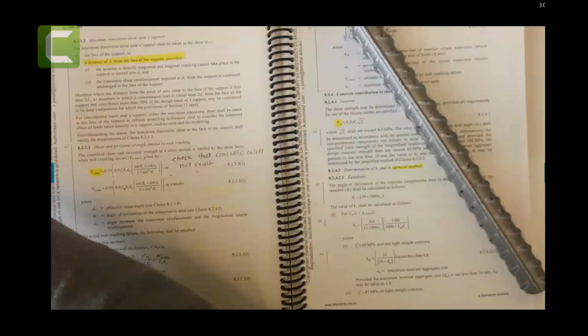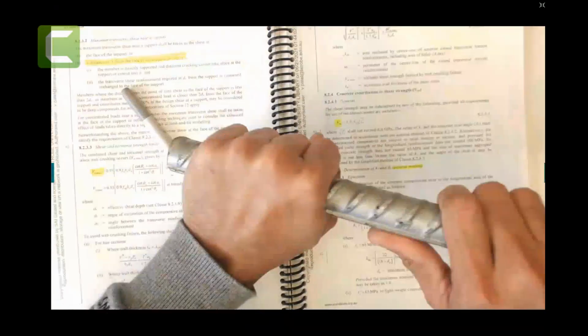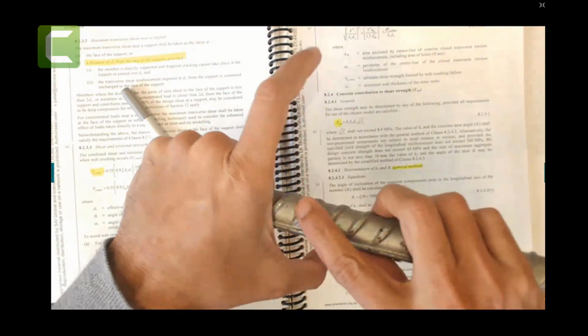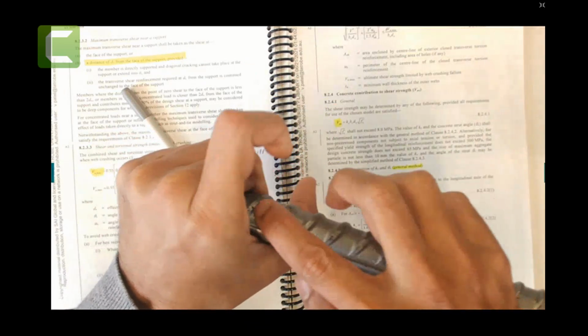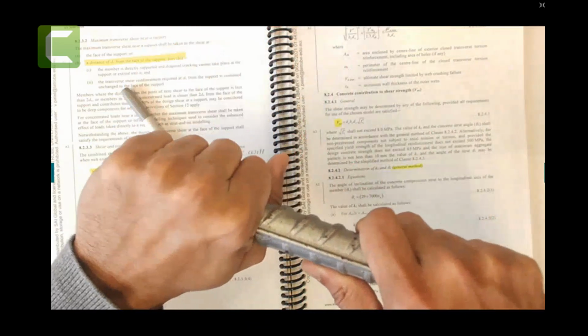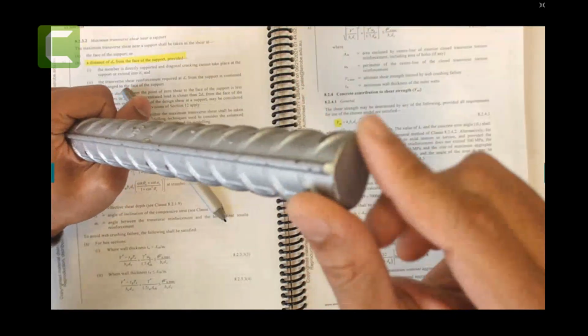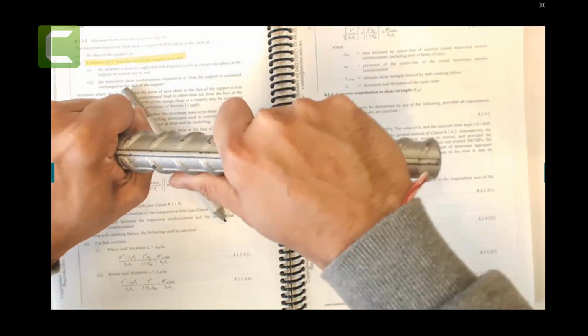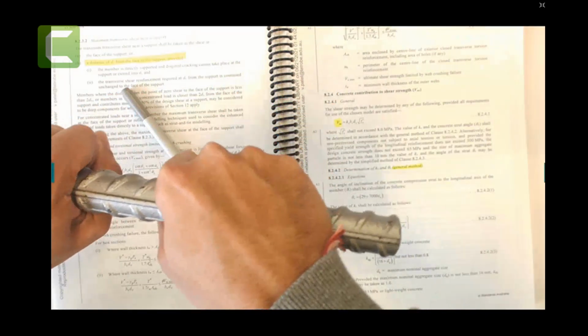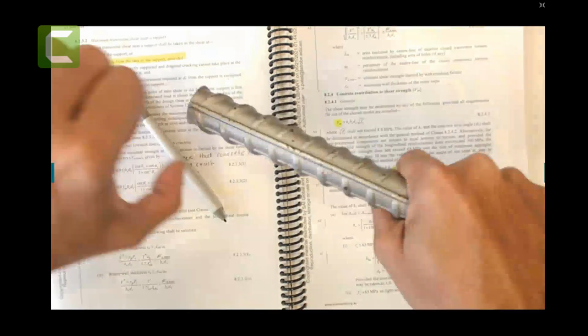So let me explain this one here in this sense: if I have a concrete, let's say this hand is concrete, I will go here, here, and here, hold it tight, and I can't go. So I'm holding it in a way that this is As, by the way, the area of the cross section. This is the yield strength of the material. This is the tension force. So area times the yield strength is how much tension force I'm going to apply. That tension force, when I apply and keep increasing, still I will not be able to remove it.